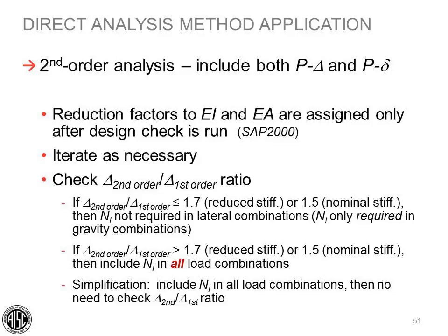So we want to check that with the highest gravity loads. Okay, great. Thank you. And our next question. If the analysis software does not automatically generate your notional loads, can the direct analysis method be used with the governing load combination only in order to reduce the number of times the notional loads are calculated and applied? I wouldn't say could be used with the governing load combination only, because there's so many different load combinations to check. If we had a very heavy structure with fairly light lateral loads, then I would be concerned if we didn't include notional loads with the gravity combinations.